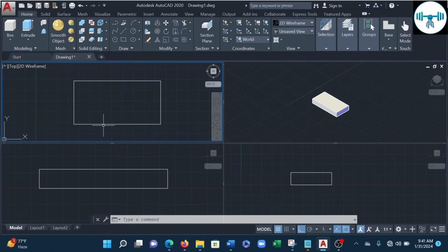Now let's assume that the cross section of this leg is going to be a square of 2 mm, or let's use the same 3 mm. So we say this cross section is going to be a square of 3 mm by 3 mm. Let's use the same square. Now look at this. We are going to draw the 4 cross sections at once, so that we are going to use just one extrude operation to extrude all 4 legs.